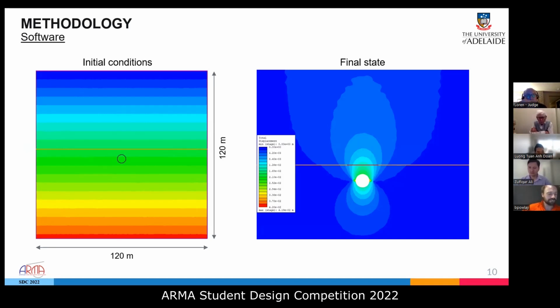There was stage simulation in Kirsch's solution and gravity-based field stress with Mohr-Coulomb failure and slip criteria. We also located the tunnel in the center of our model, and used 8 times the radius away from the external boundaries, which have fixed conditions, to reduce the likelihood of boundary influence.